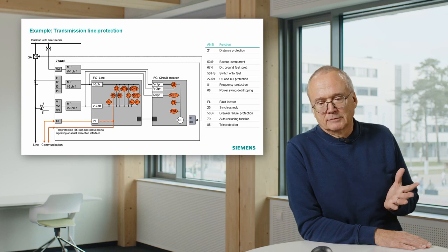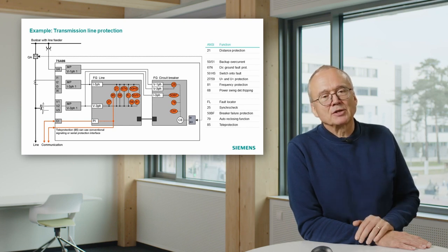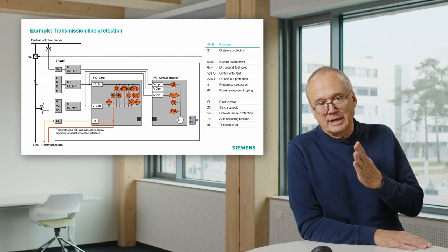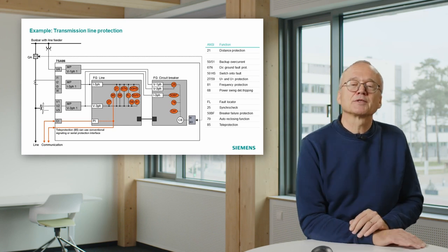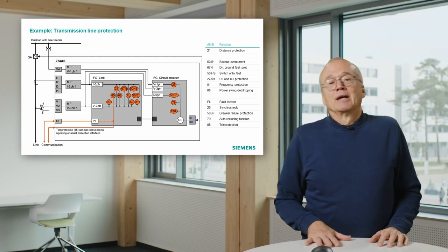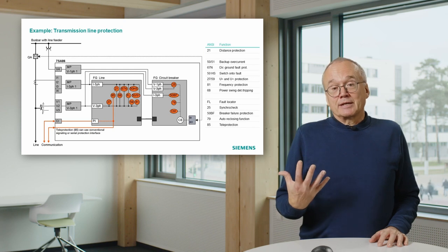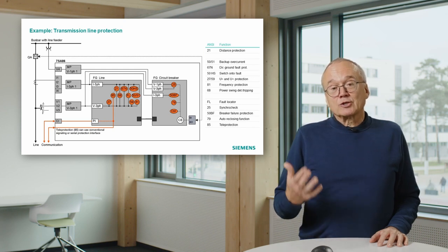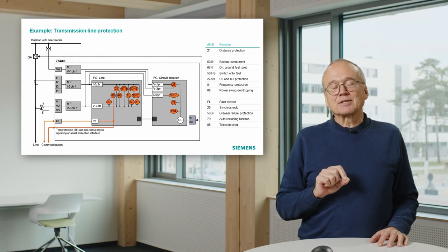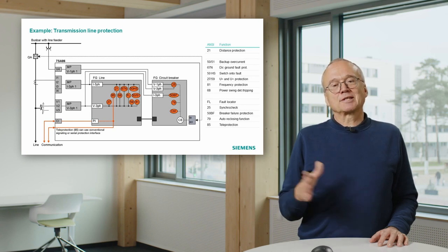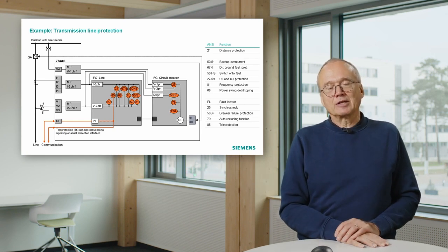The reason there is, I mentioned it already, we have always in transmission systems the star points grounded. That means distance protection will react on phase to ground faults, but it has limitations in sensitivity. We will see that in the following videos.